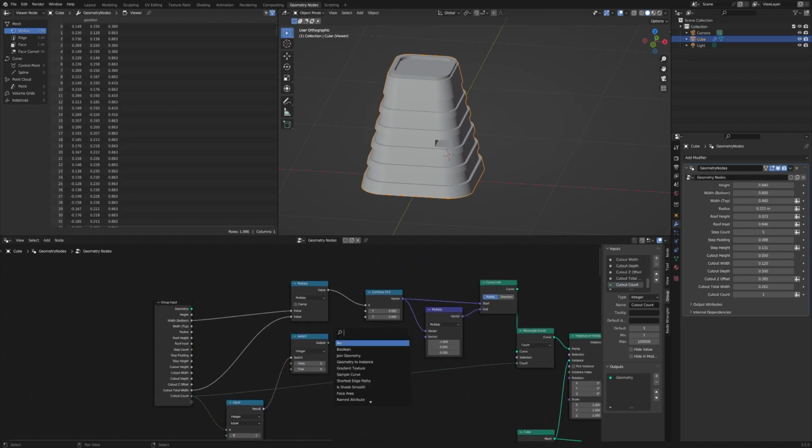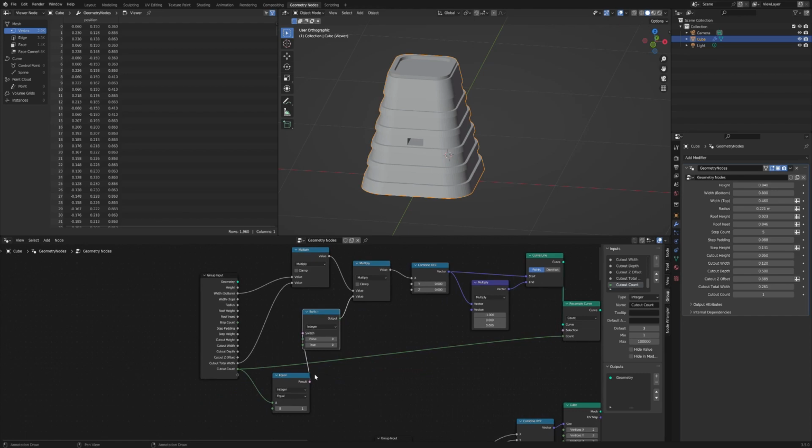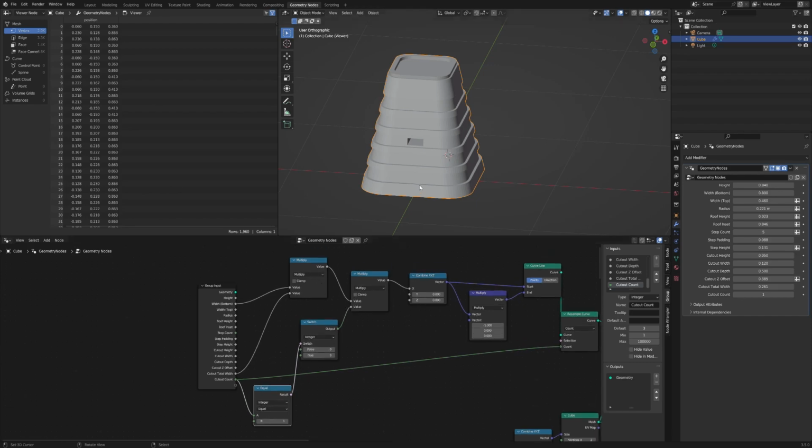So then we can do a vector math node. Actually, don't even need a vector math node. We can just use a normal math node here. Multiply is actually what we want, so that's good. And we can put the output into here, and you'll notice that centralizes now. Because what's happening is the 1 is coming into here, it's compared to 1, so therefore it's true. It's coming into true, which is 0, so it's actually just multiplying whatever x value we find by 0, i.e. centre it.